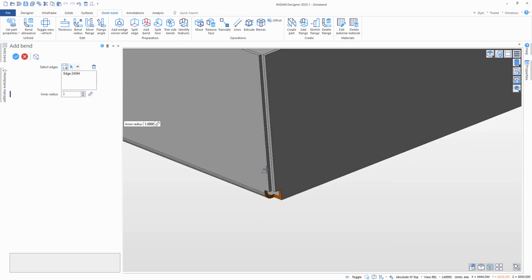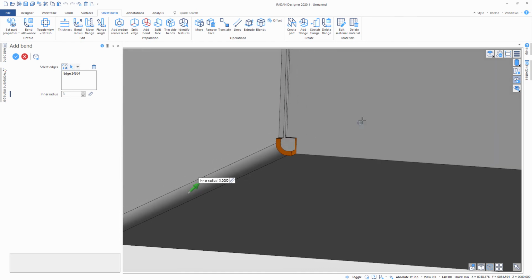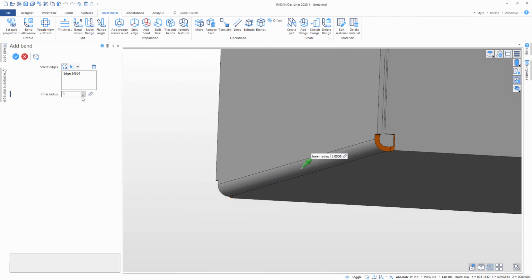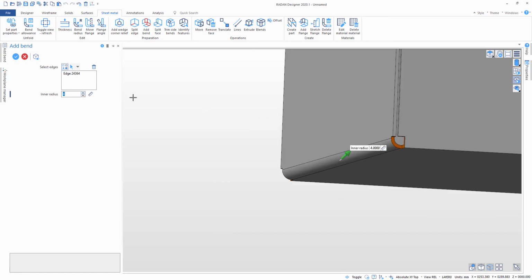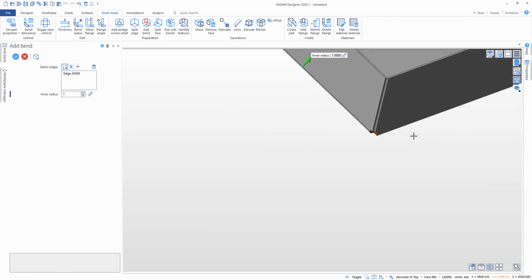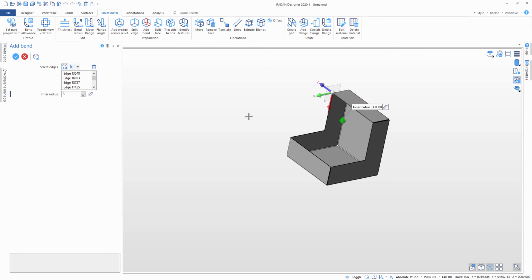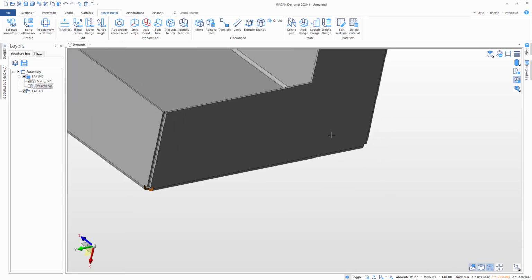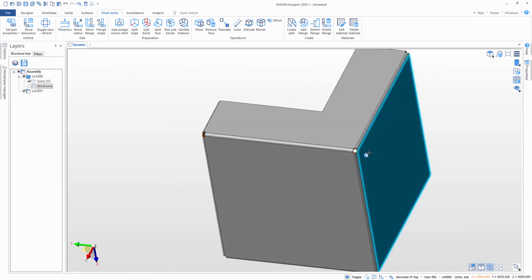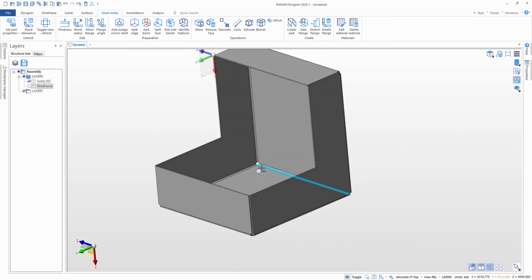If you pick an edge, it creates a bend geometry. So here we can choose what the radius is. So let's say I'll go with 3, or we can, if the model is appropriate, box select everything, and we convert all of the remaining edges into bend geometry.